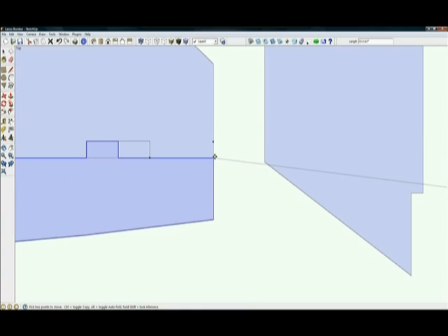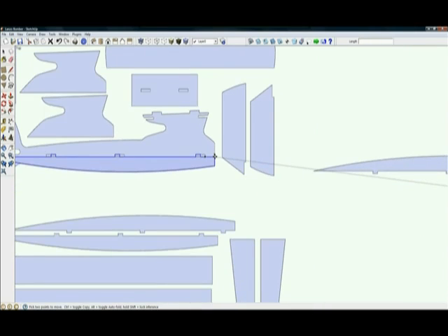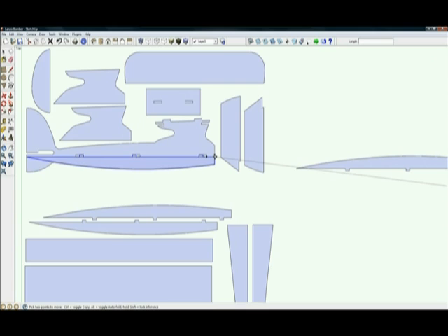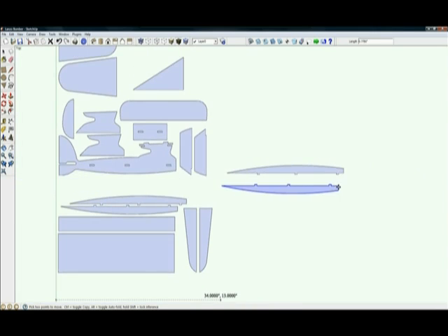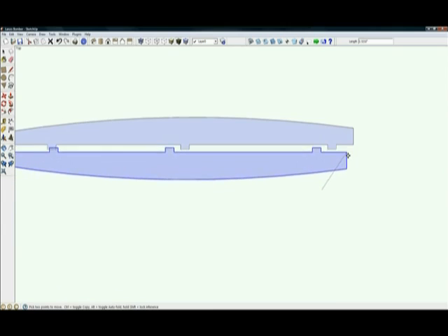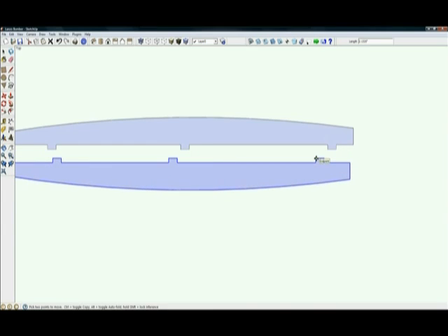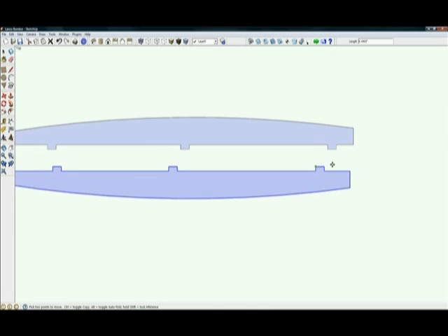And you can see here, and I don't have these made as components, so I can't move my mouse around, but the bottom piece that's shaded is showing how the right side stiffener would go in and then utilize half of that slot width for fitting in, and it leaves the other half open for the other side. And it allows us to have the fewest number of slots and the greatest number of tabs. Everything just fits together real well. And since these are burn pieces, I'll show you how you can do that right here.